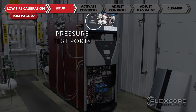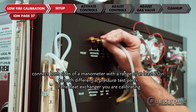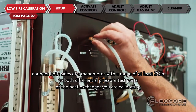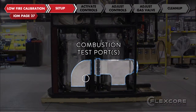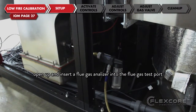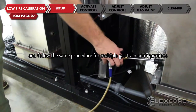We will now calibrate the blower speed and combustion values for low fire. Connect both sides of a manometer with a range of at least 20 inches to both differential pressure test ports of the heat exchanger you are calibrating. Open up and insert a flue gas analyzer into the flue gas test port, and follow the same procedure for multiple gas train configurations.